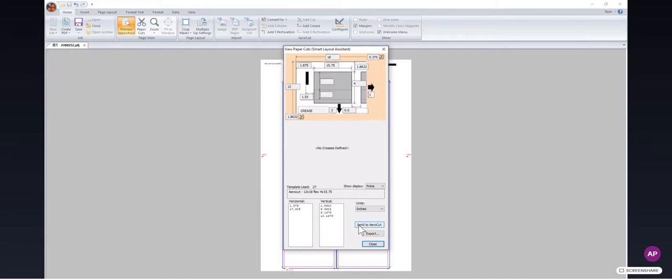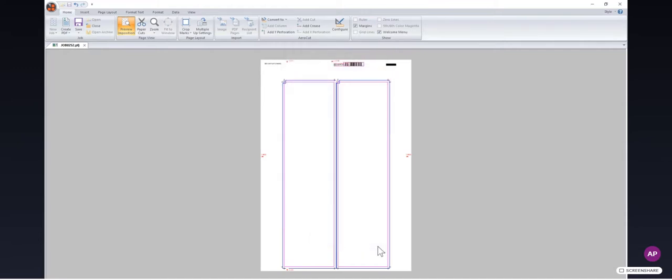Today, though, we're actually going to be converting this ManuSet job into Flexmode. You can create Flexmode completely from scratch, because in Flexmode, you program in every single action yourself, so you have complete control over the layout. I think it's much easier to do it this way, because by converting it to Flexmode, all the cuts are already pre-programmed for me, and I can just add things like perfs and creases later. So I'm going to go to Convert to Flexmode.